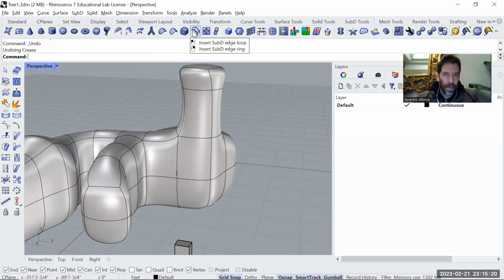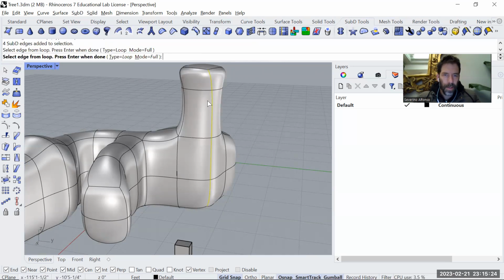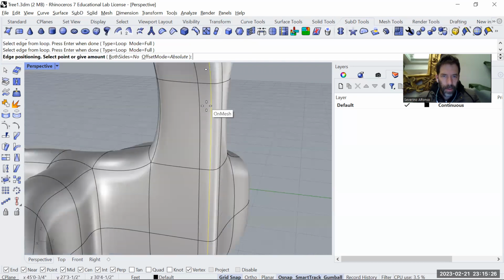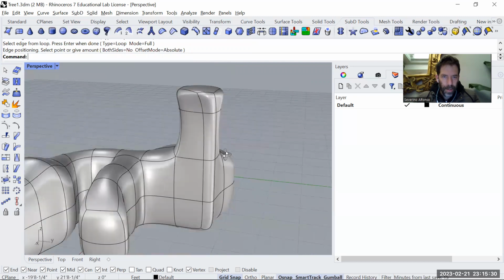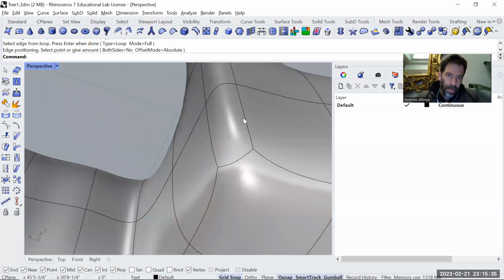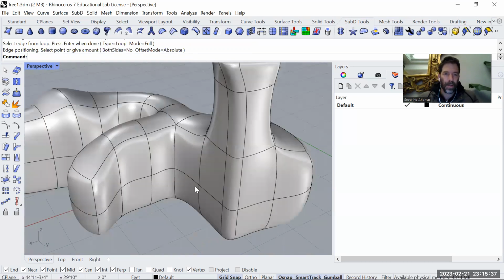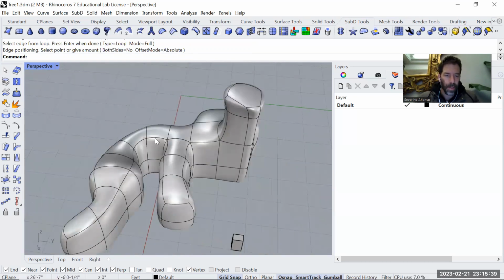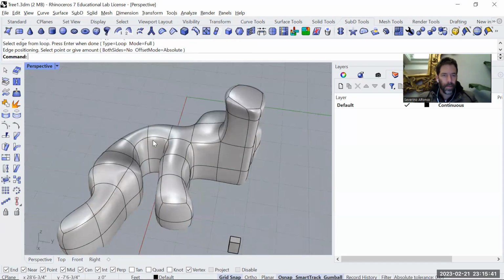But you can also create the edge loop. So if you say edge loop, Control C, double click that one, you can create basically 2 edge lines close to the one you created here, to give a sense of sharper smoothness. For example, if I double click here, Control Shift, double click that line, it's going to do this line, and I can